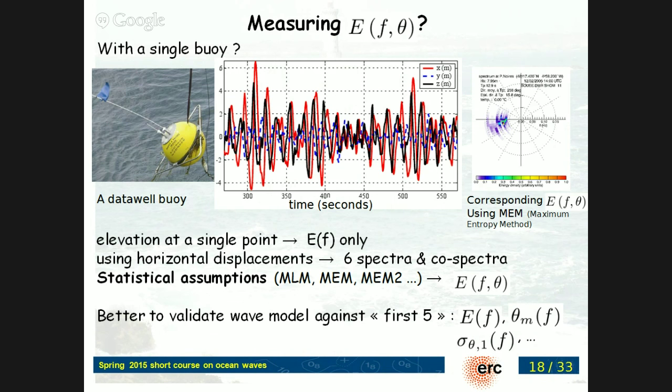So this buoy measures the motion of the sea surface. It has accelerometers inside, and it's measuring the acceleration in three axes, so the X to the east, the Y to the north, and the up. And that's a typical record of the buoy data for a few minutes. So this is 240, so 6 minutes. No, 4 minutes. And you can see it going up and down, and you see the wave groups, some big waves and small waves and big waves and small waves.